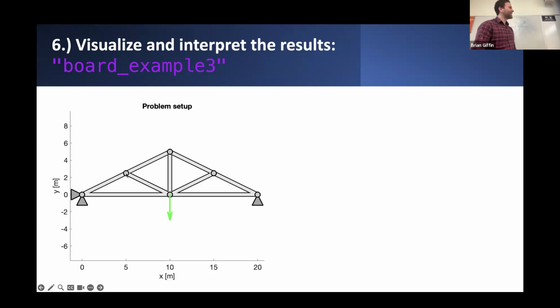Yeah. Similar reasoning behind that. If we have two forces that are supposed to be balanced with each other here and here, and we have just one force acting in a direction that's perpendicular to those two members, there'd be no other force that could balance with whatever force is coming in from these members. So they do have to be zero force. Good observation.